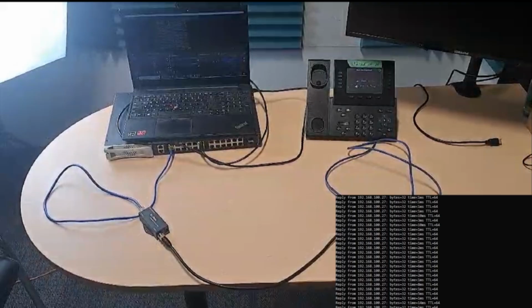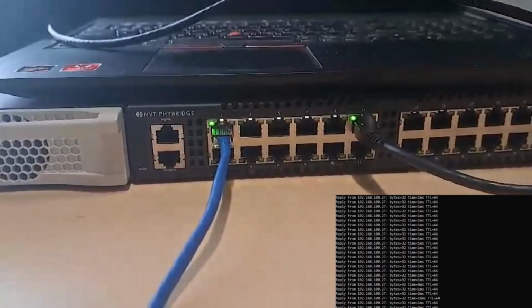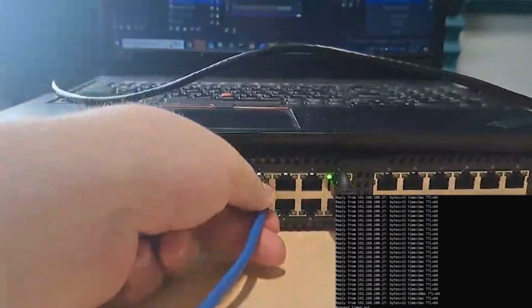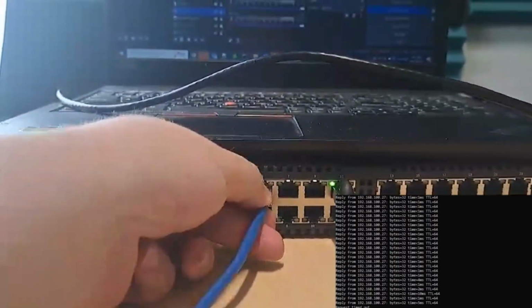There's always the possibility that the fault lies within the cabling itself. Removing the components from the installation and connecting them using a short, 3-foot patch cable is a great way to substitute for the main run. If the system begins working after removing only the cabling from the installation, we can begin troubleshooting the cable by checking its specifications and verifying terminations. You can also test the PoE switch by swapping the connection to a different PoE port. If the issue is resolved, we can confirm the fault lies with the original port on the switch.